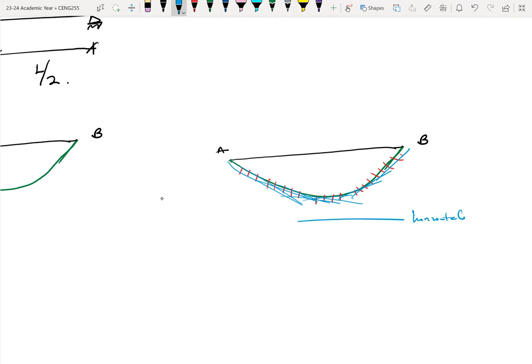Okay. Which means that if that happens, then the slope at that unknown tangent, so let me use the letter K for that unknown tangent, is 0. So if we can find that particular point for these types of curves where the slope is 0, that would also give us the maximum deflection at that point.